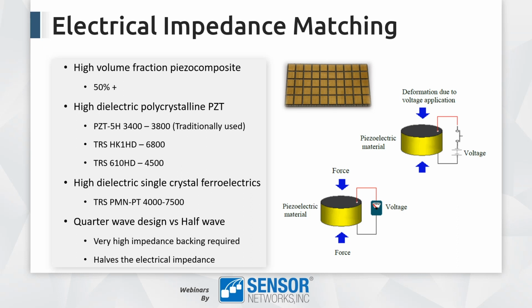There's also recently been a lot of work in single crystal materials, and we're just starting to look into this. Unlike polycrystalline PZT, which is traditionally what everybody uses, these materials are actually grown crystals or oriented crystals of PZT. They have better performance, better bandwidth, and they also are available in these high dielectric materials. So that's another thing that's been primarily driven by the medical community to improve matrix array performance, is single crystal materials development, which is now widely being used in medical transducers.